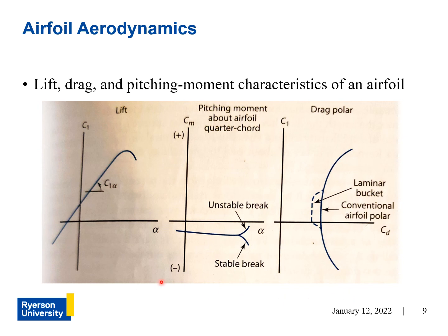So here we see how all three change with respect to angle of attack. This one is called the drag polar, and it's expressed in terms of lift simply because sometimes it's easier, or more useful, to see the variation of drag with respect to lift instead of angle of attack. But the idea remains the same. It shows how the drag changes with different flight conditions.